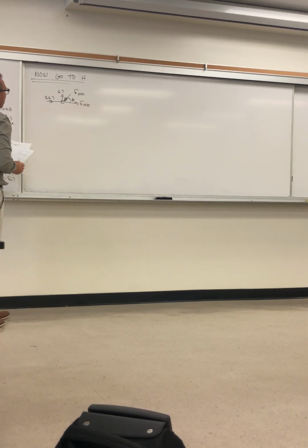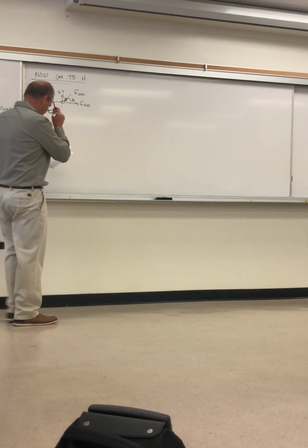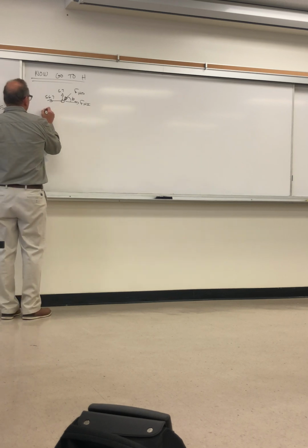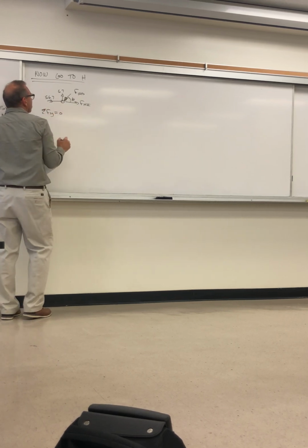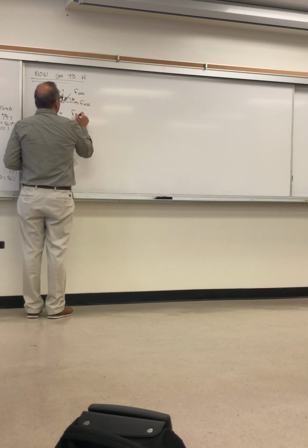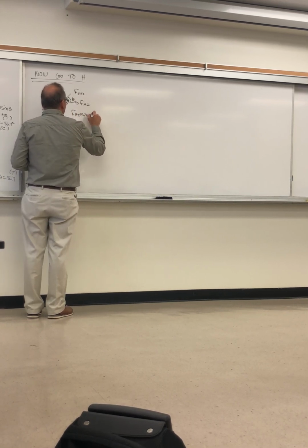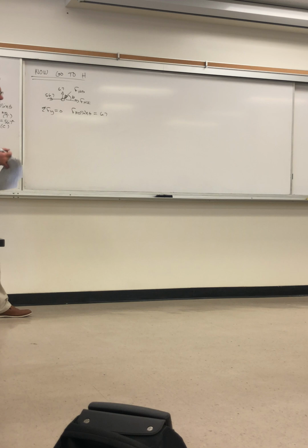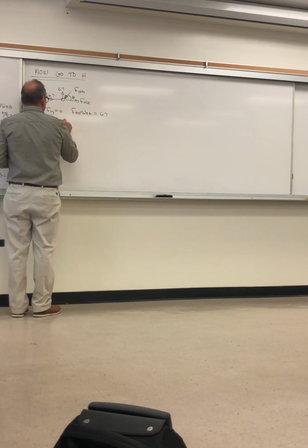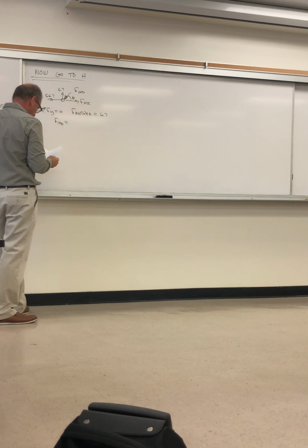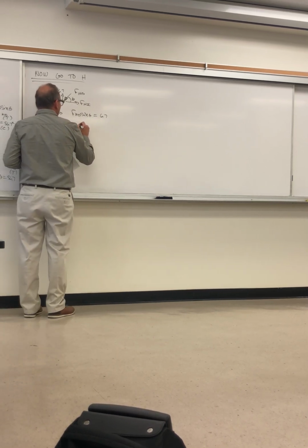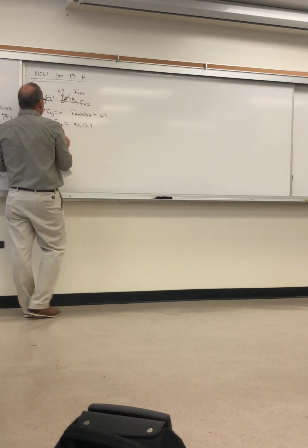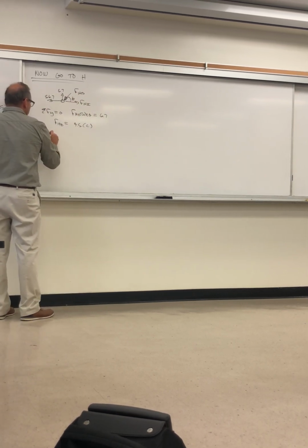Okay, no vertical loads applied at the joint. So that's at H. When we get to I, we have 10 kips down, so we'll have to include that. Summation of forces in the Y is 0. F of HD multiplied by the sine of theta equals 6.7 up there for it to be balanced. So F of HD is 9.5 kips, and that's in compression. That's this force down.